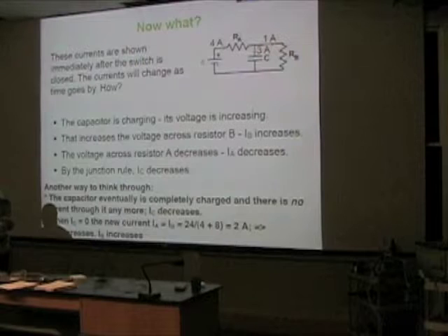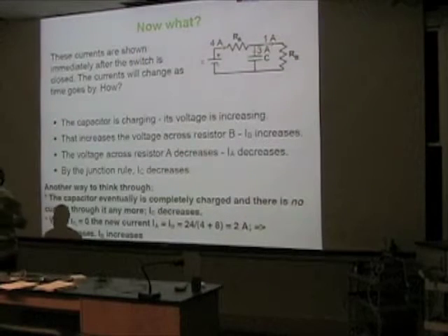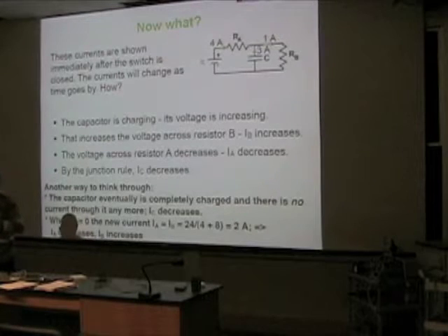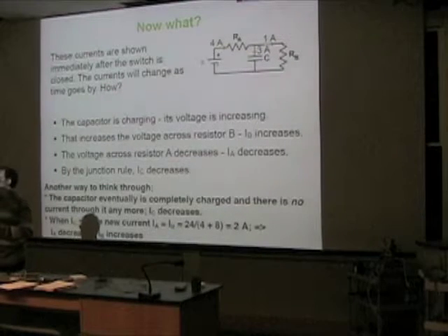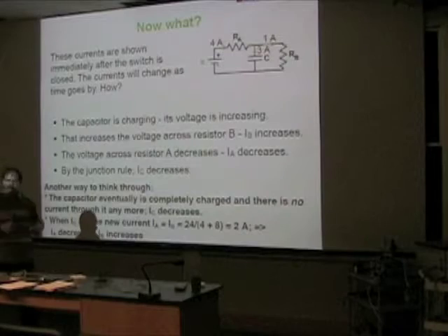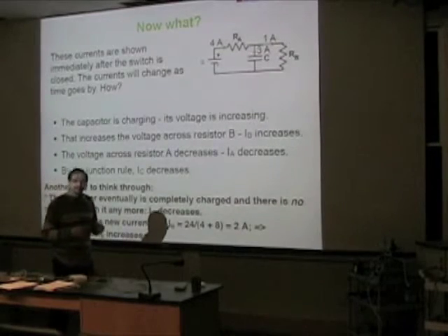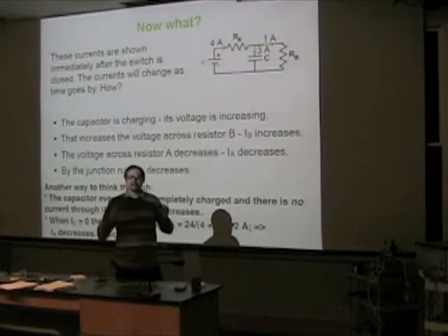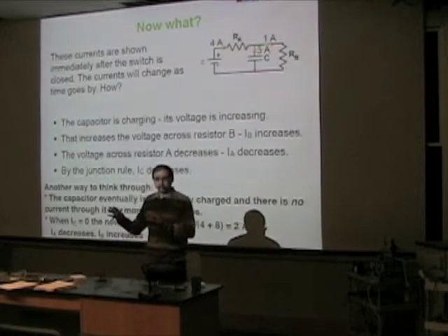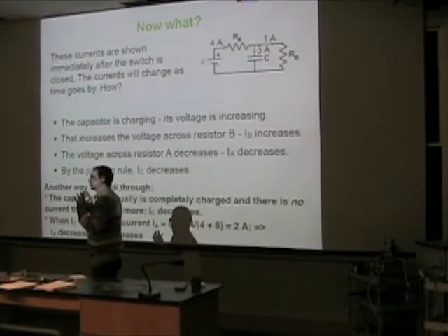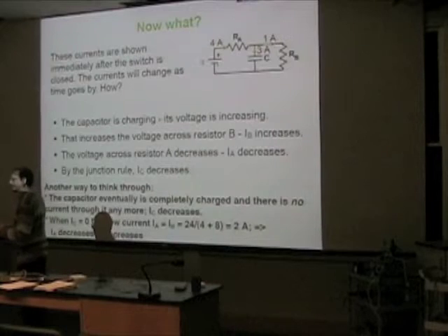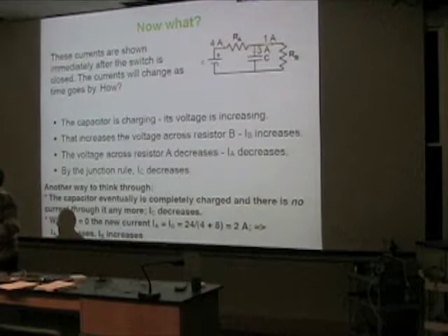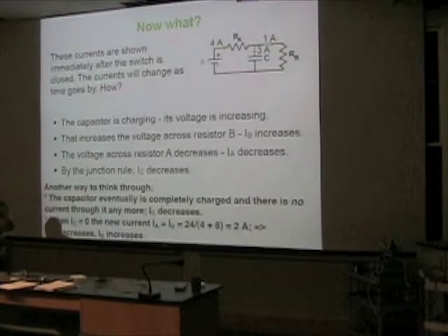We know how everything should end. Eventually, there is no current through the capacitor. Always, no matter how it starts, if we wait long enough, the capacitor doesn't have any current anymore. Because the voltage stops changing, that means charge stops changing, no change in charge, no current.